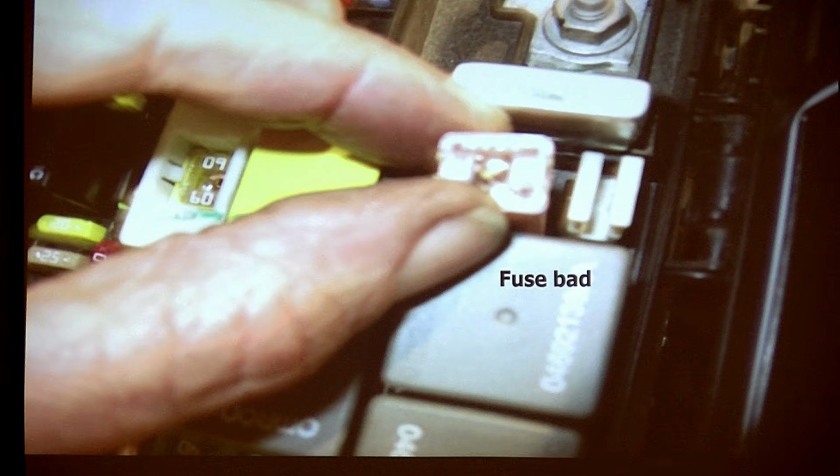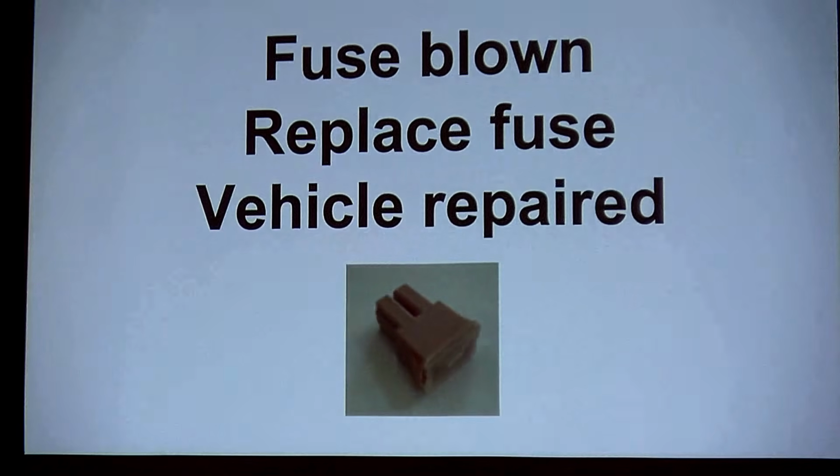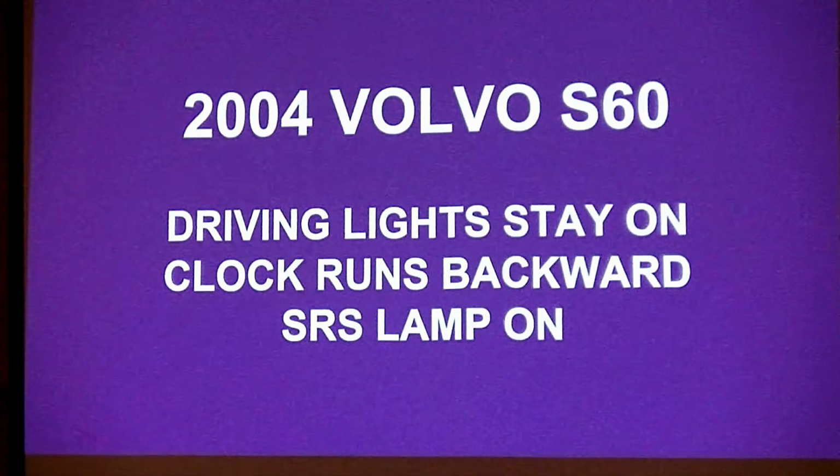The fuse is blown. That's all that's wrong with this car. It's just the fuse. So I didn't have to figure out the comm wires, but that doesn't matter. I could have done that, couldn't I? It's all a step. It's a procedure. Stay with the procedure. Don't get confused. Put a fuse in it, it fixed it.